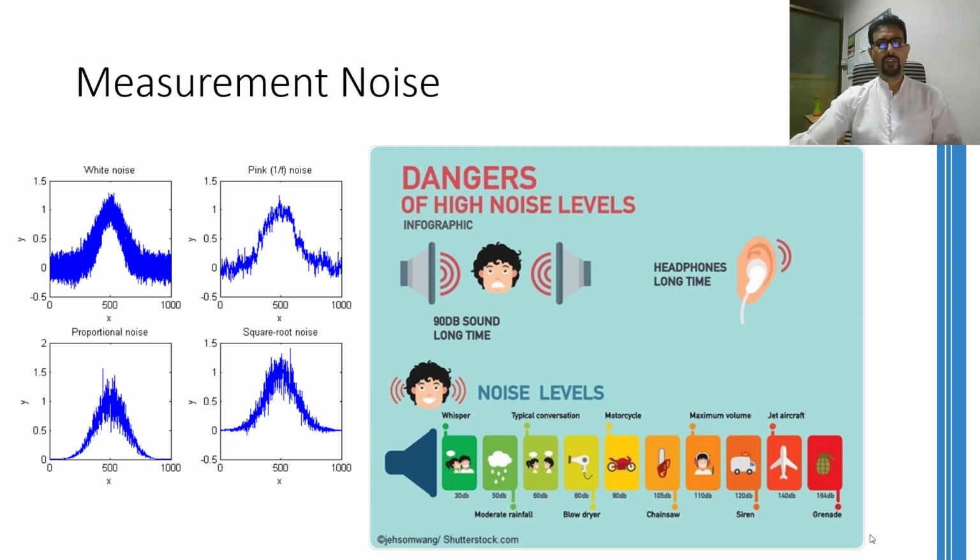In this portion of the lecture, I'm going to talk about the noise or error that can be induced into our sensed signal when you are moving that signal from one place to another. It can be from the sensor to some processor, or from one processor to some remote processor or logging facility. Majority of the noise induced in this situation comes from interference from other components of the measurement system or from components placed near our measurement system.